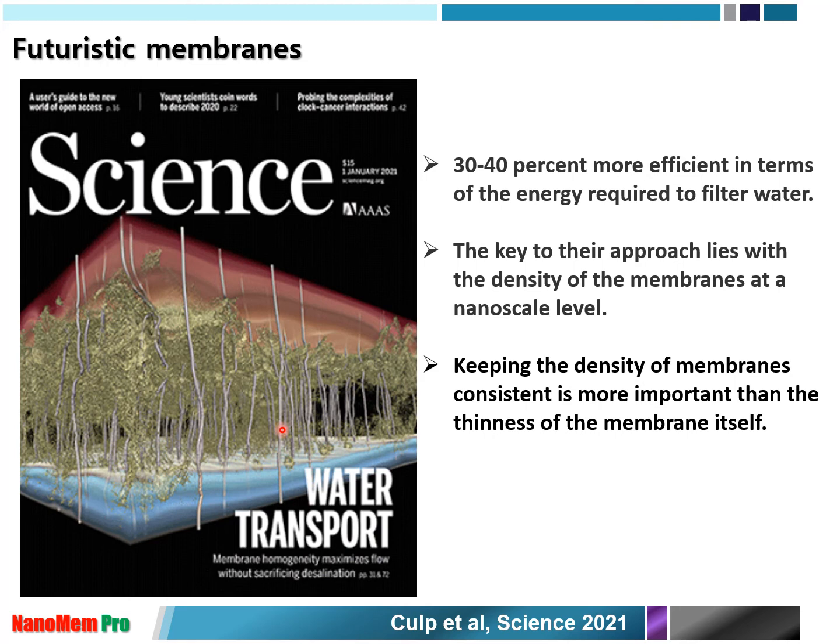A series of polyamide desalination membranes was synthesized on an industrial-scale manufacturing line under varied processing conditions but retaining similar chemical composition, showing increasing water permeability and active layer thickness with constant sodium chloride selectivity.